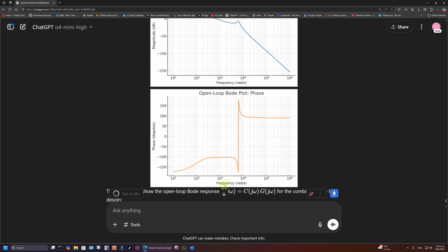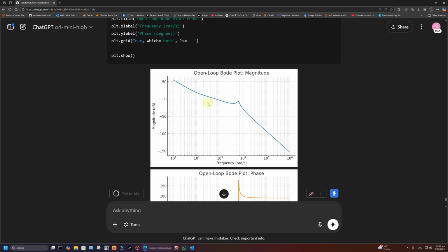Here we go. Oh, it's done it, wrapped the phase again, which is really annoying. That's not bad though. So this is the gain margin here between 0 dB and that. That's about, oh gosh, what is that? About 10 dB or something. 10 dB of gain margin, something like that. Even 6 dB would be fine anyway. Maybe.